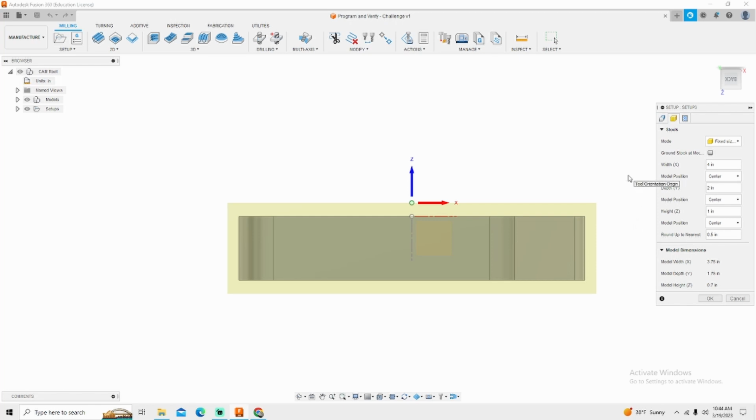If you're in metric, typically go millimeter, millimeter and a half. But again, for today, it's saying I need a 4 by 2 by 1 inch part. And my preferences within my profile is set to the nearest half inch. That gets me as close as I need to be, and honestly and truly, it's close enough for what I do. I could go down a size. It's actually going to tell you your model dimension right here. And honestly and truly, that's just not enough.